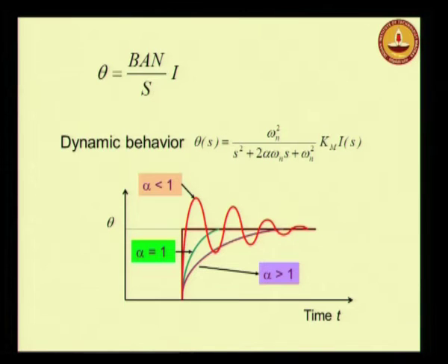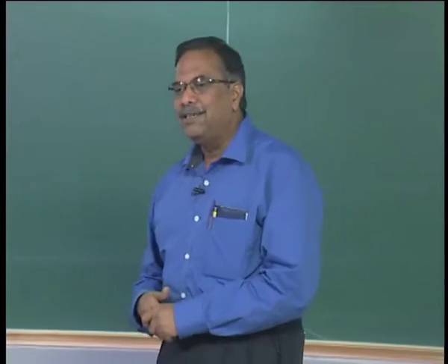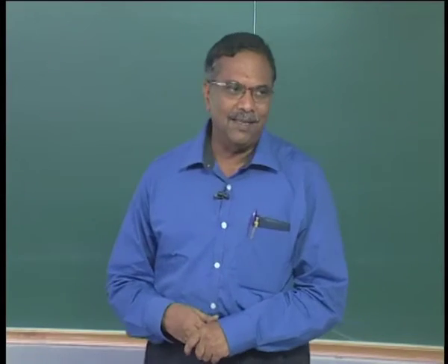The constant is dictated by the flux density in the annular space, the area of interaction of the coil with the magnetic field, the number of turns in the coil, divided by the spring constant, the constant of the springs that restrain the coil from running away.